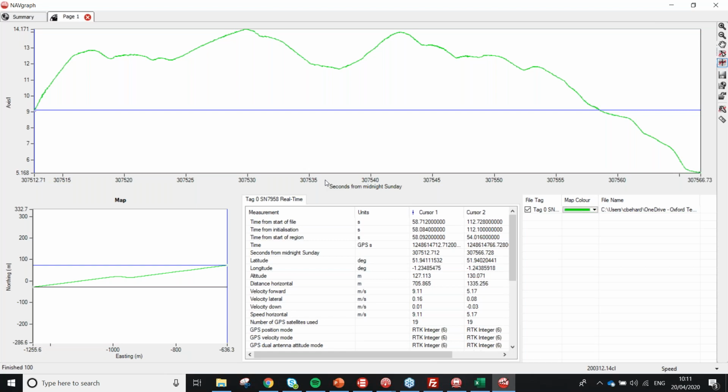Okay, thank you. Is it possible to post-process multiple files with the same settings, or do you need to go through the GUI for each single file? Unfortunately, the RT range post-process doesn't have a batch process option. So you can't process multiple files with the same settings with one click. You'll have to go through all of the files.